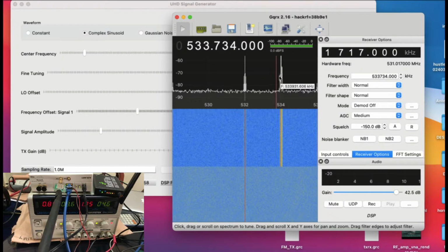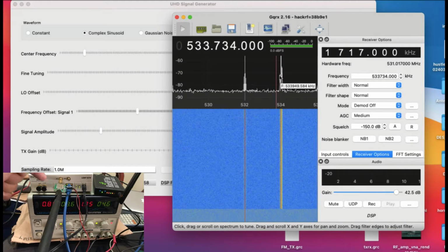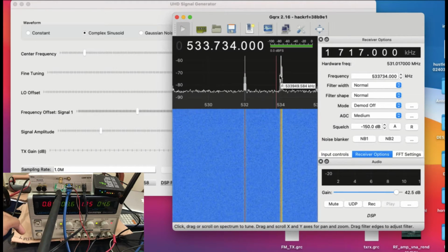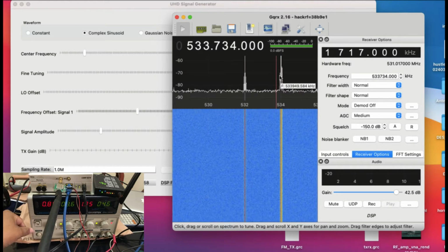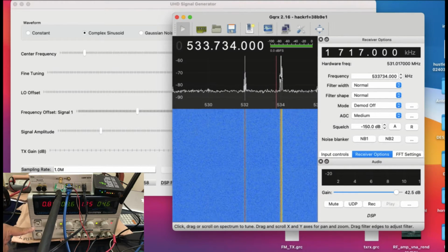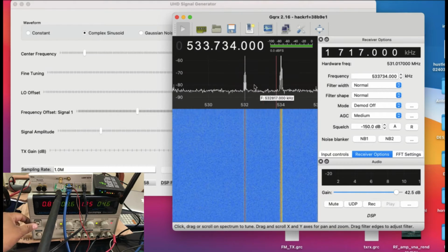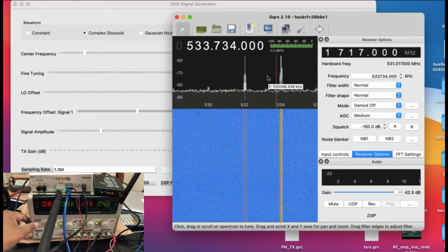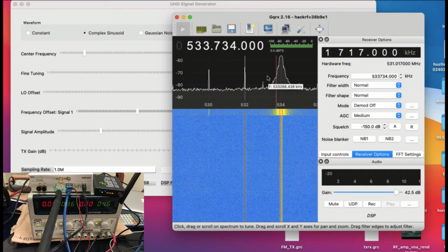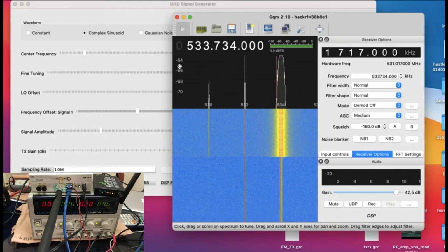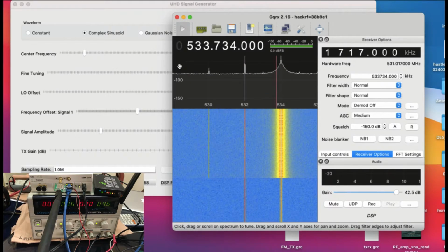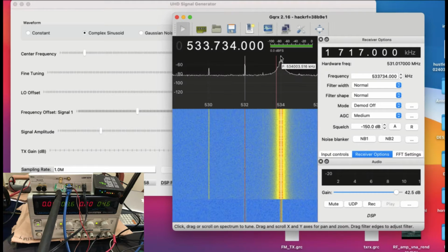All right, now the next step is this. If you were to look at my antenna, it's connected via a power amplifier, and it's not connected to anything else. So it's just connected, but power is not turned on. The biasing is not turned on. So I'm just gonna simply turn on the power, and then you start observing what's going on in the flow graph. As soon as I turn on power, you can clearly see amplification taking place. Right? You can clearly see my signal has jumped.